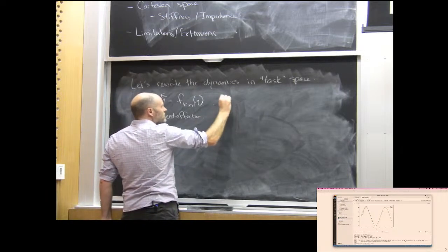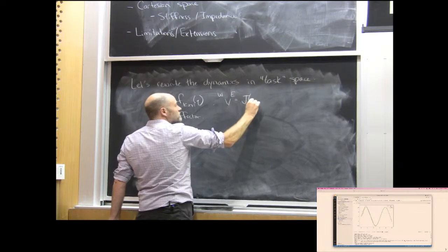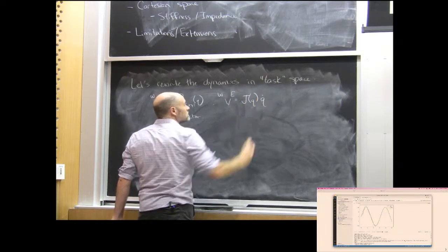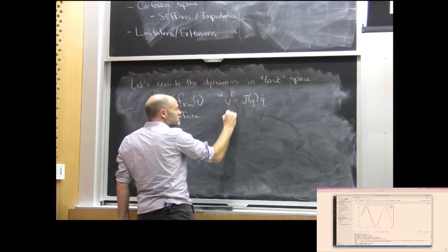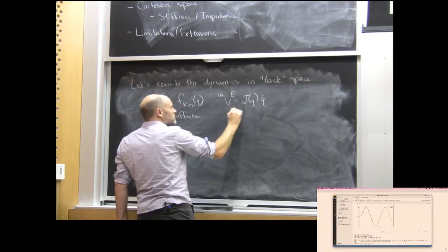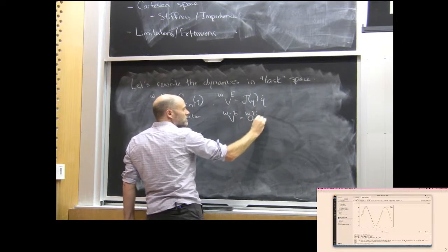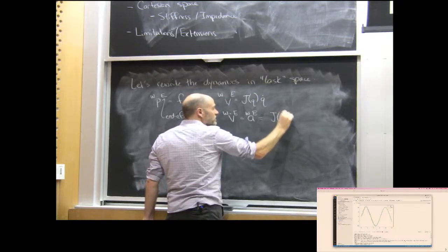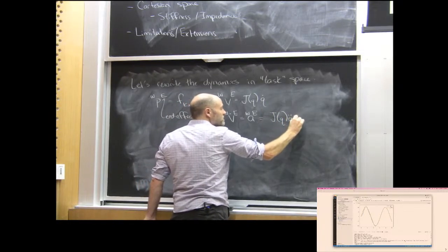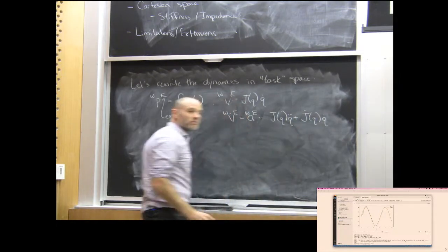My velocities are related by the Jacobian. My accelerations also have the relationship, v dot of E, which we actually have multibody notation for, calling that A, and that gives me, if I take the time derivative one more time, this plus an extra term, J dot Q dot.